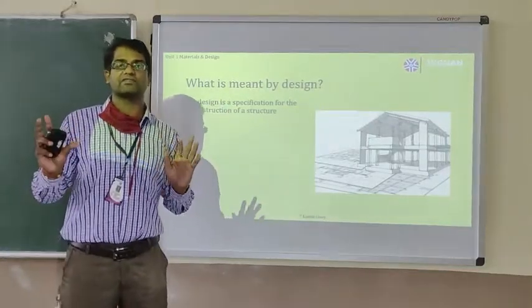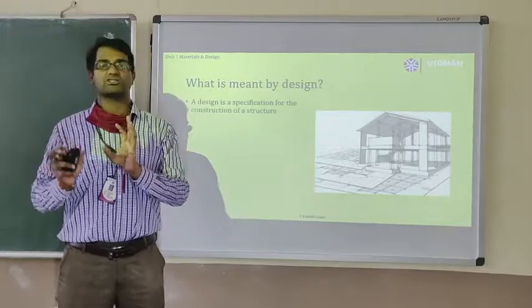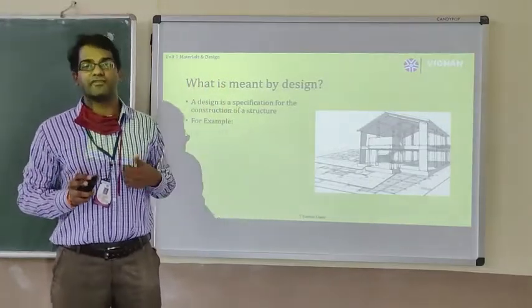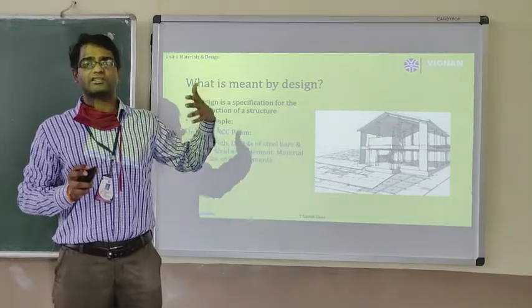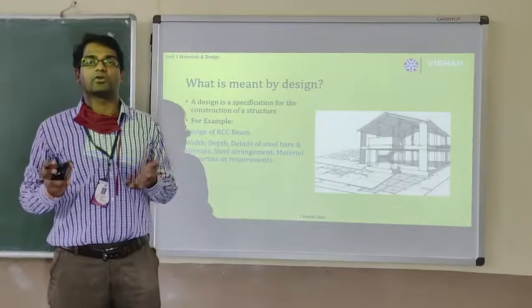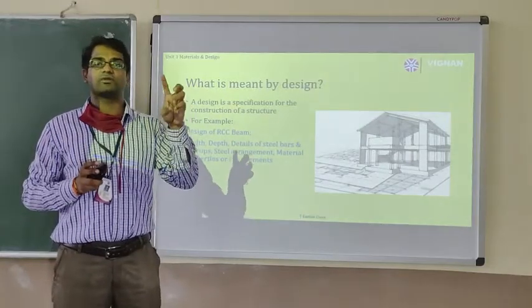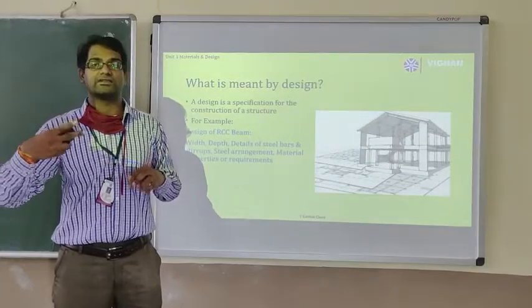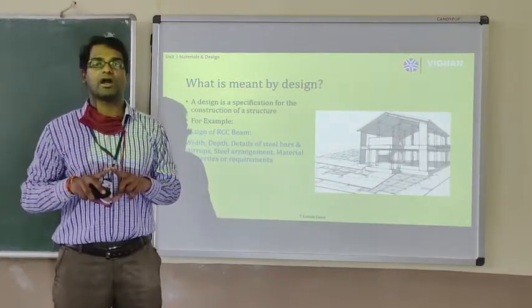So in our civil engineering we call that structure a construction. Designers are also available in many fields. For example, if you are designing an RCC beam, what will you give? You will give the width of the RCC beam, you will give the depth of the RCC beam, then you will give the steel details, the number of bars you need to have, right?